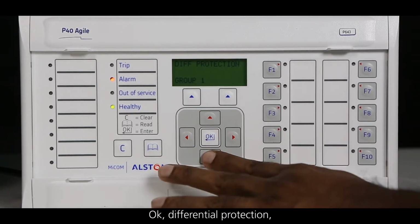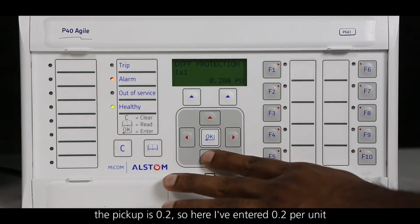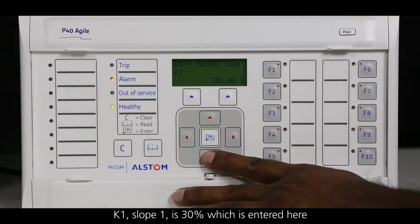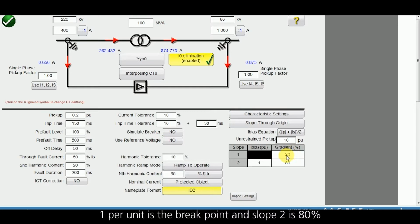Okay, differential protection. The pickup is 0.2, so here I have entered 0.2 per unit. K1, slope 1, is 30%, that is entered here. 1 per unit is the break point, and slope 2 is 80%. And the characteristics equation is (I1 + I2)/2.